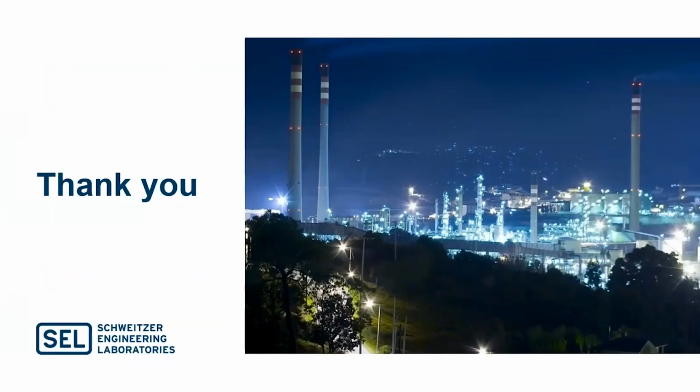Absolutely. The PowerMAX utilities is capable of detecting simultaneous contingencies. The contingencies can be defined as single event contingencies or N-1, such as loss of a single transmission line. The contingencies can also be defined as double event N-2, such as loss of two transmission lines, and so on. So yes, the simultaneous detection is possible. Thank you very much.